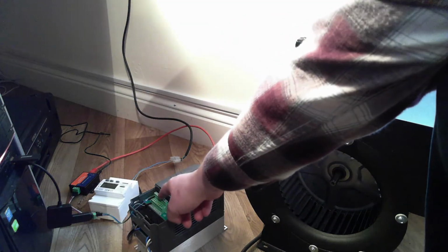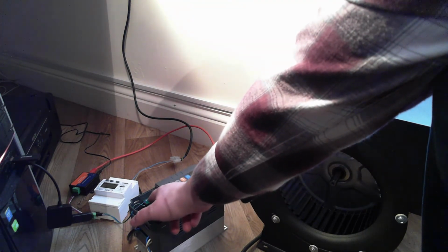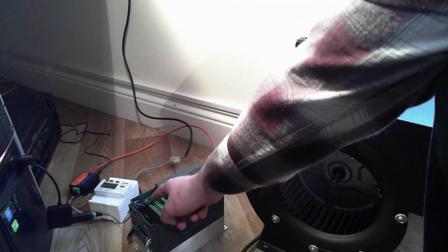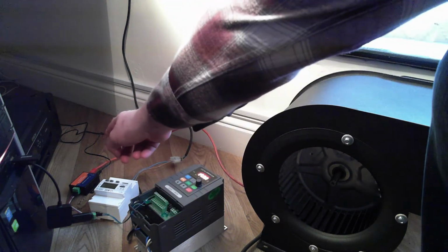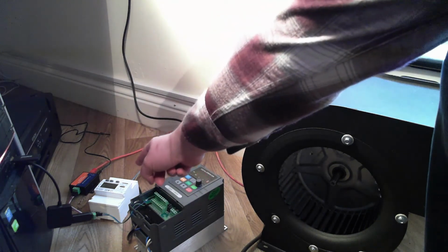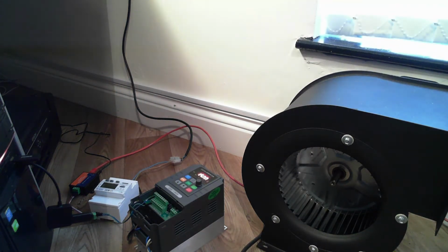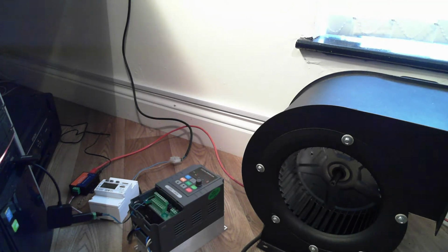The USB to RS485 is controlling the VFD, and it's only wired up where you can see these two wires that represent the minus and the plus, or A and B, of RS485. The exact same is done across here with the energy meter, which is just pulling back the basic values of current and so on. This setup is just to show both of those communication methods, for the purposes of gaining that kind of control.